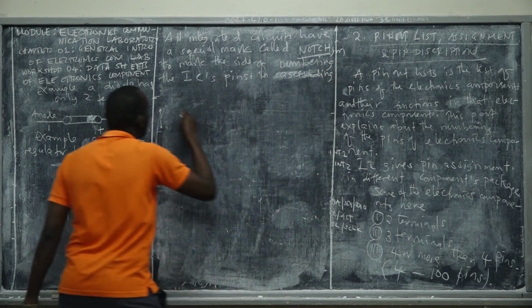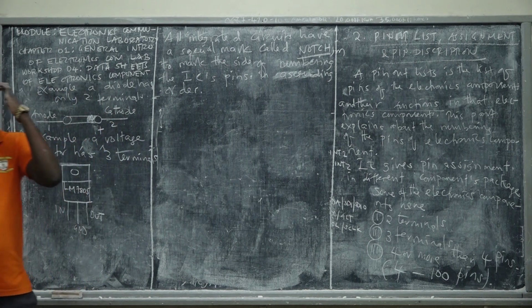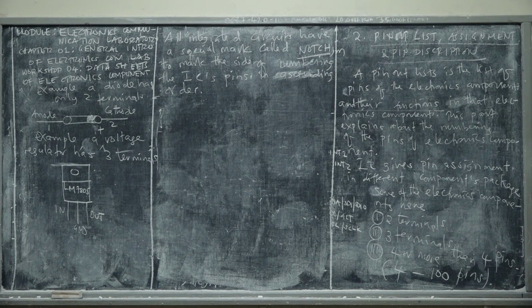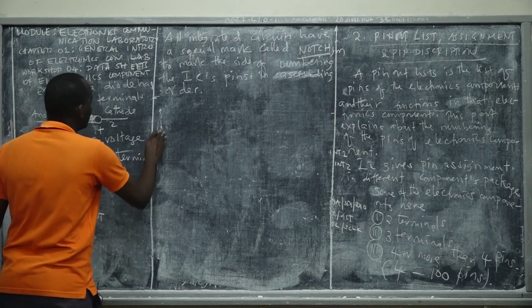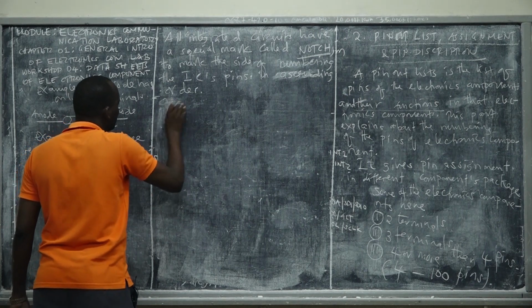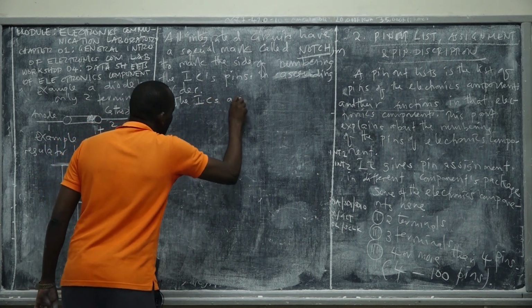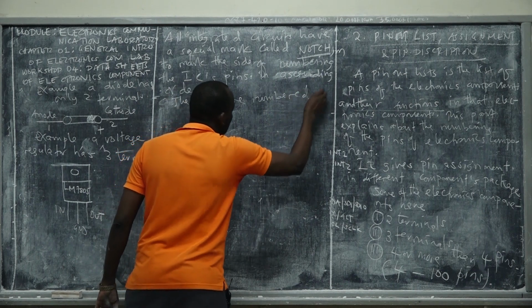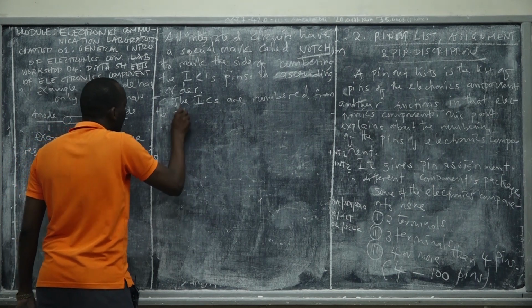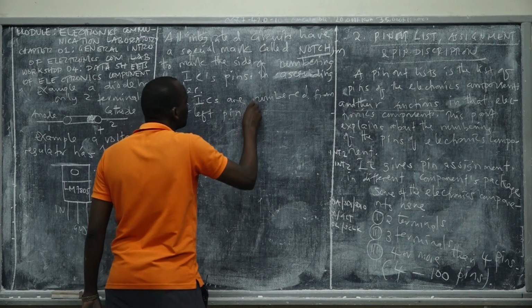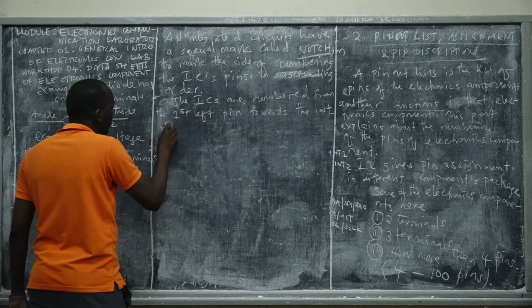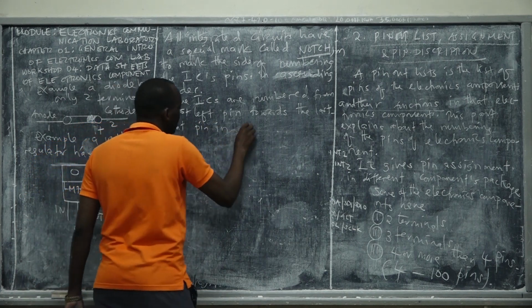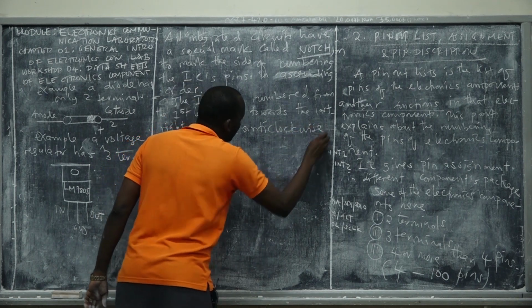So if you have an IC and you don't know about its pin configuration, the best place where you can get clear knowledge is its data sheet. Right? So the ICs are numbered from the first left pin towards the last right pin in anti-clockwise direction.